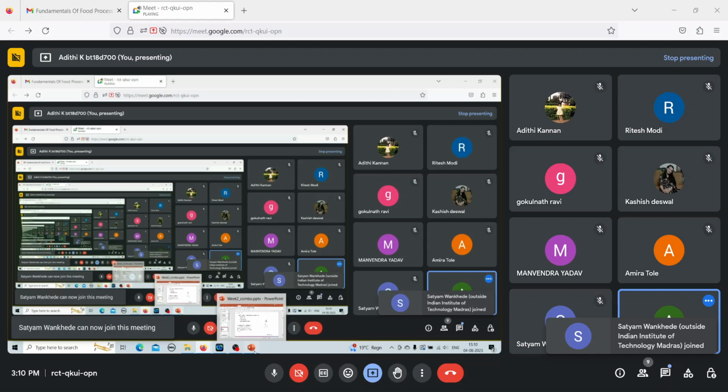It has both elastic and viscous nature. So this part is because of the elastic behavior, this part is because of the viscous behavior. So you will see that the stress slowly drops even though you maintain a constant strain. So this is exploited in stress relaxation. So the answer is option B.